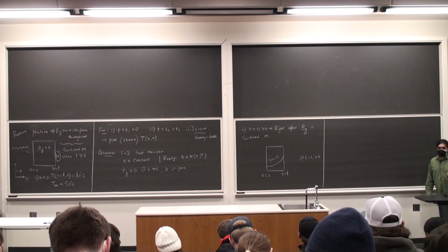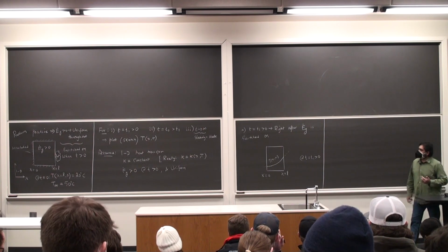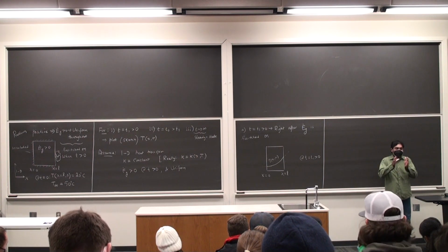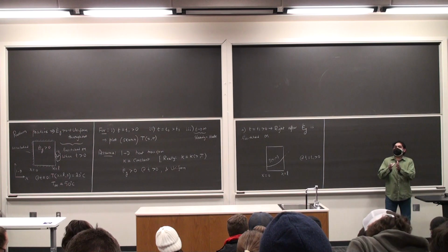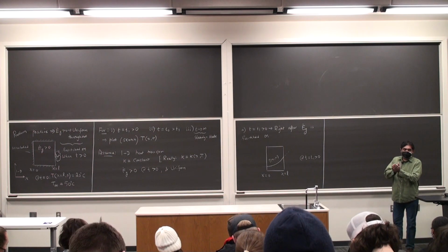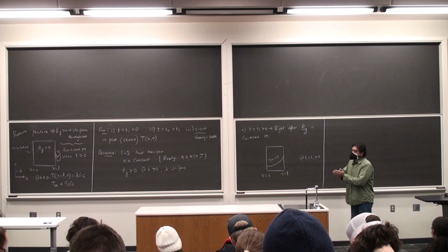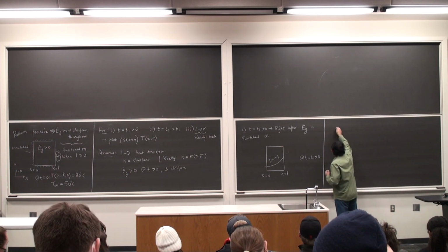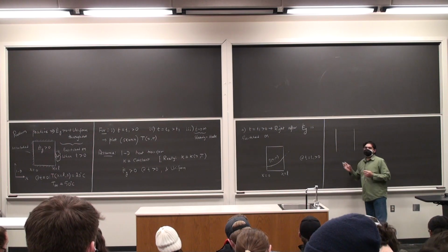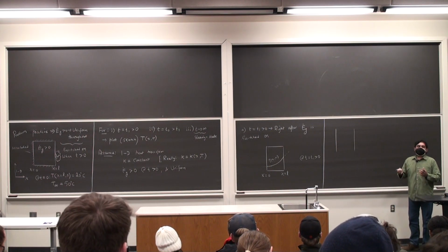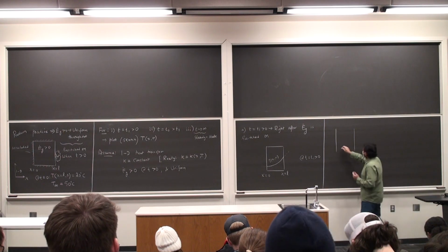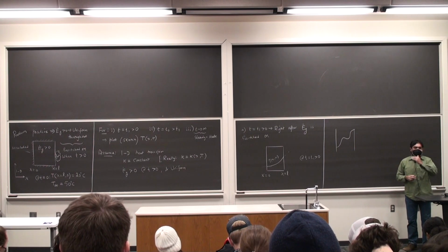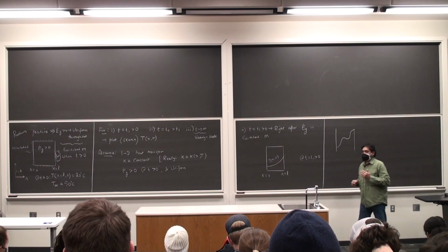Couple of things I want to point out. This is kind of cheating because we have really not solved the heat diffusion equation, the full-blown heat diffusion equation, which is including the time effects and the spatial effects. But what you will find out is that if you solve the one-dimensional heat diffusion equation, I'm just drawing some random temperature profile, you cannot have things of the sort happening. You cannot have things like this happening. And still a continuous curve. It's smooth and continuous, it is differentiable, C infinity and all that.